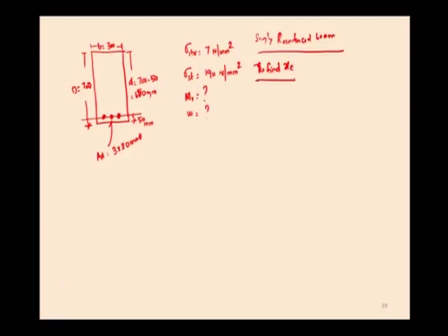That is the critical depth of neutral axis. xc divided by sigma cbc is equal to (d minus xc) divided by (sigma st by m). This is the expression for finding xc. Here Ast is given in the problem, that is 3 numbers of 20 mm diameter bars, 3 into pi by 4 into 20 square, which is 942 millimeter square.